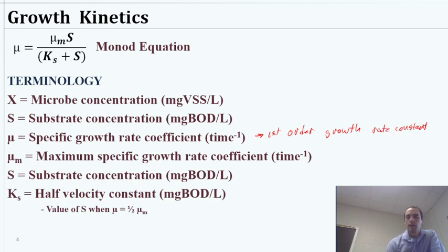So what we're looking at with this Monod equation is a lot like the case when we did flocculation, and we had the K, the rate constant that determined how quickly the particles are going to meet each other and therefore reduce the number of particles. And it relied on several other things. Here we have a K, except it's a mu, that relies on several other things. Okay, so that's what we're looking at in terms of an equation here.